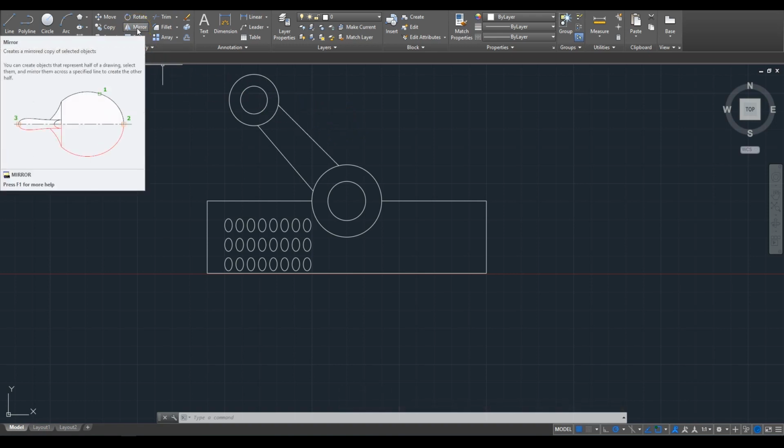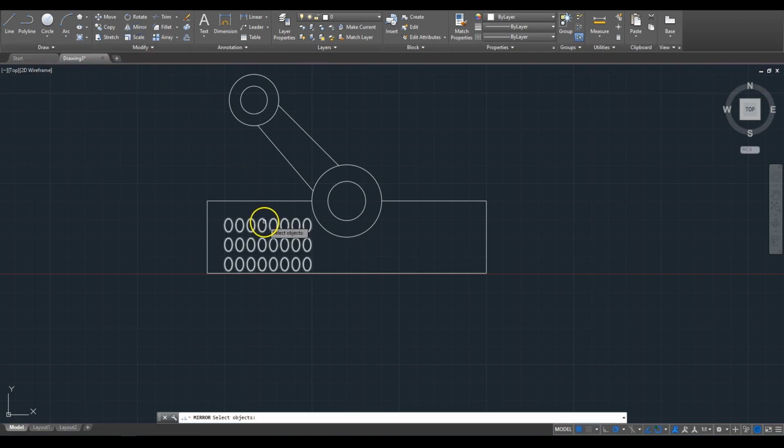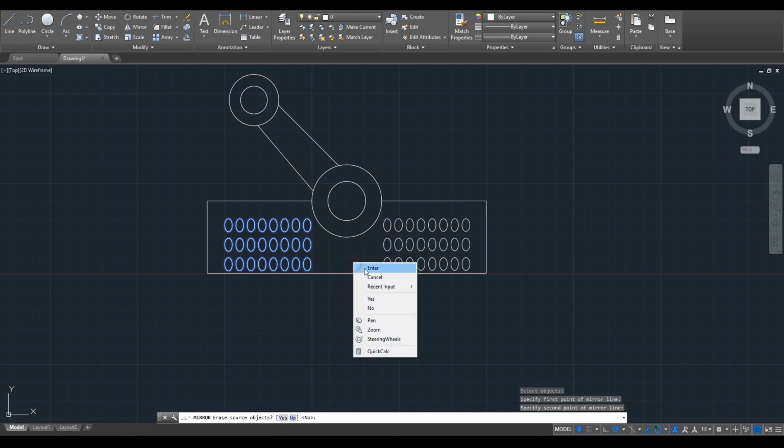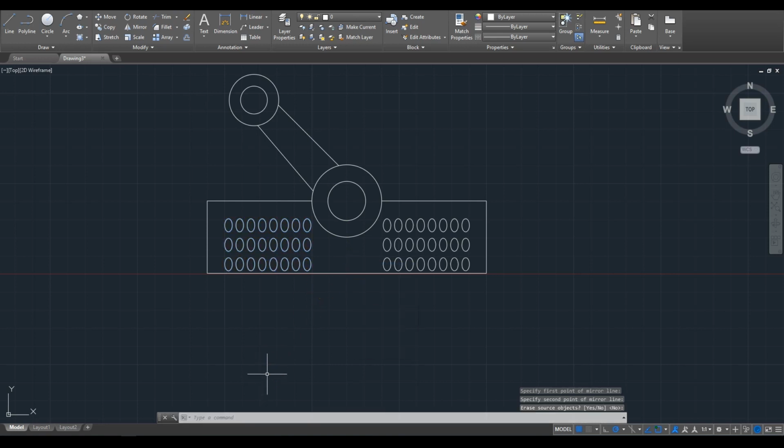The mirror function works by selecting your objects that you'd like to mirror, closing selection, and then drawing a mirror line. For closing out the mirror command, it asks if you'd like to keep or throw away the existing selection. Please select yes or no based upon the desired results. After mirroring an array, each array is its own entity, able to be modified to your desired specification.